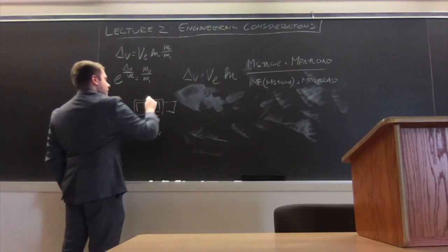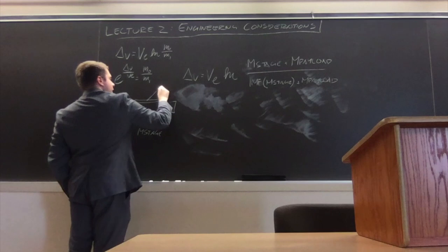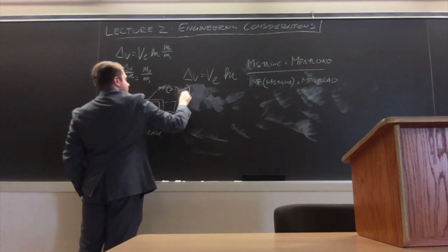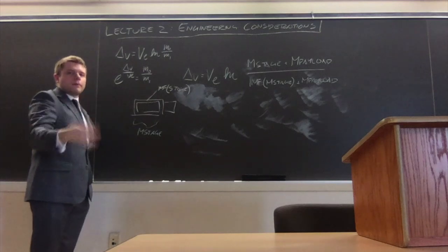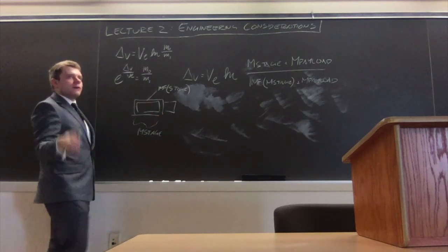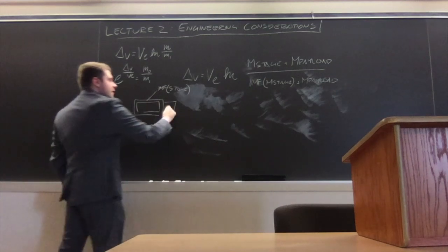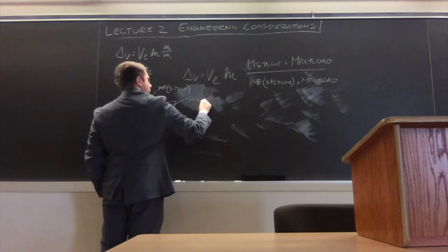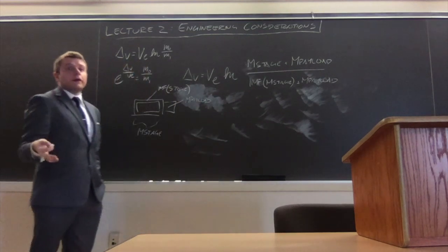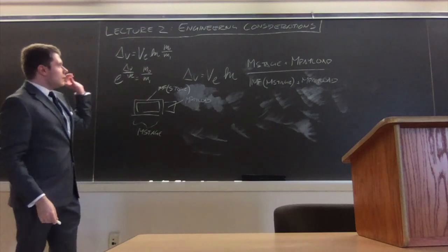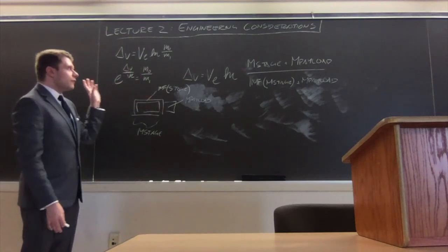The inert mass is the mass of the tankage, residuals, plumbing, everything that's not burned up but still part of that stage, and a function of the total mass of that stage. And there's the payload, which is what we actually care about. It's the satellite or it's another upper stage of the rocket. Now, you'll recognize that the next step here, because, well, this only tells us their delta V.